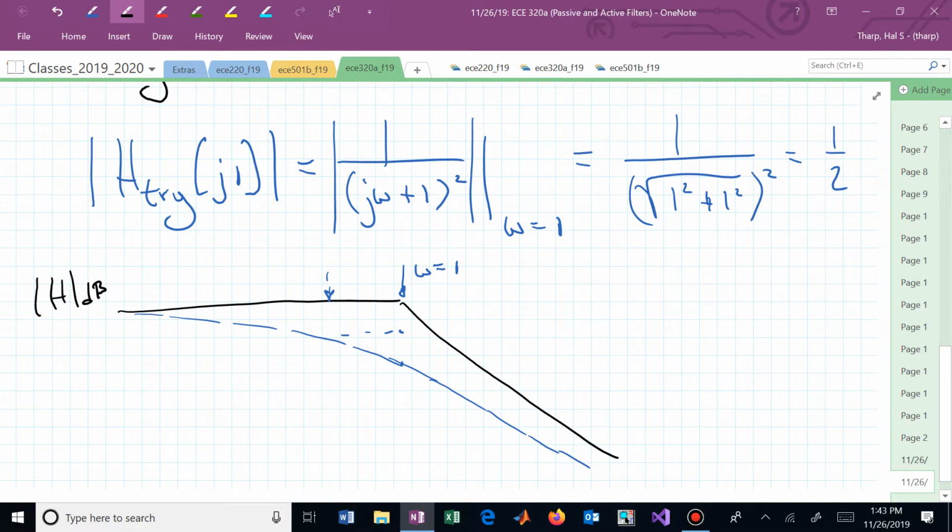Well, we want to try to maintain this flat magnitude response as long as we can, and then bend over right at the last minute and go through the same frequency of 1 for any of the order of filters we want to design. So we want our magnitude plot to be flat, maximally flat, and the way that we do that is with Butterworth filters. Do you see the pancake reference? So we have Butterworth syrup that we put on these flat as a pancake.